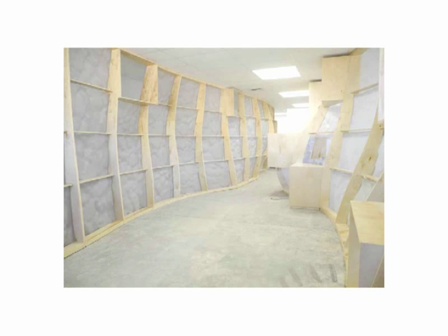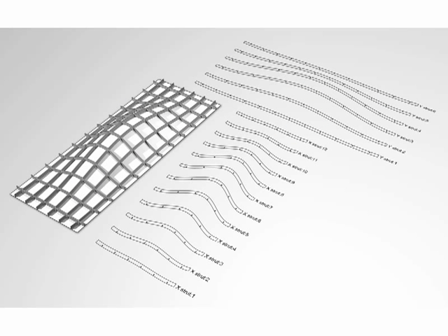This isn't the same project, but it's very, very close to it. It's the same architect though. So scaled up. Again, the idea of waffling is that you have some form that you've created, you take sections of it, and if you can see, these are cut in the top chord, and these are cut in the bottom, and when you lay the top ones into the bottom ones, they fit together, they get you your waffle. You don't really see those as joints, they kind of disappear into each other, okay?